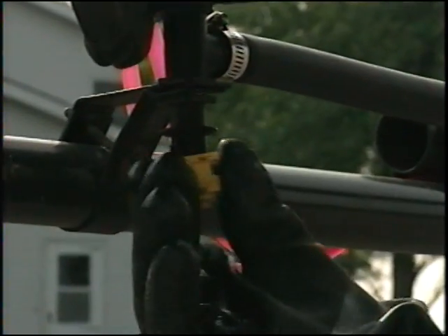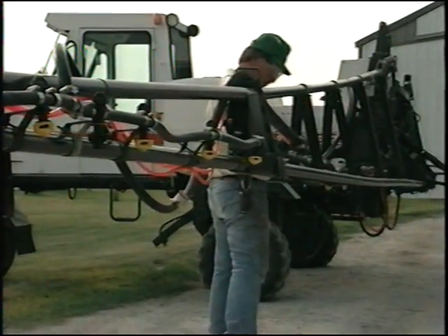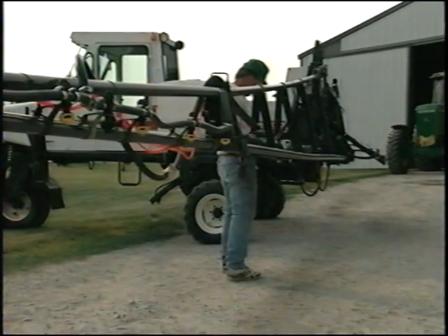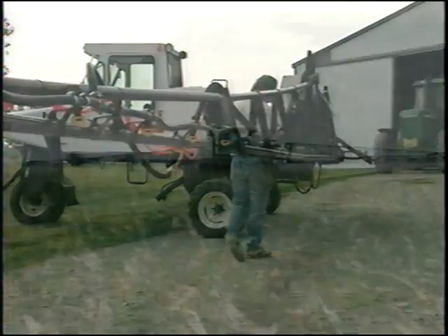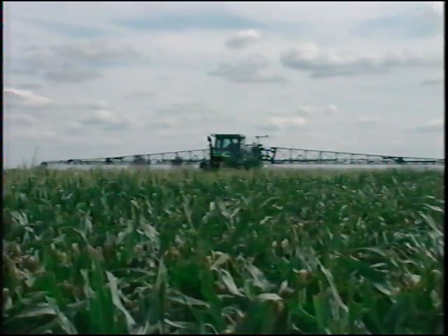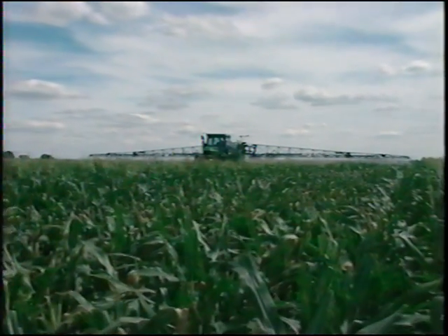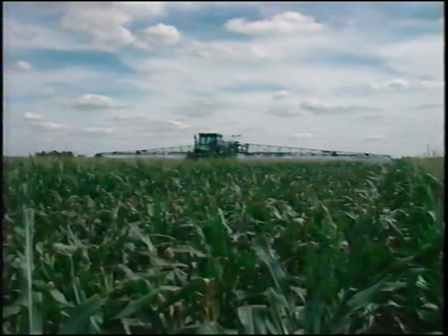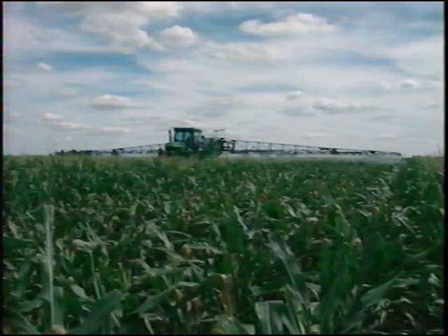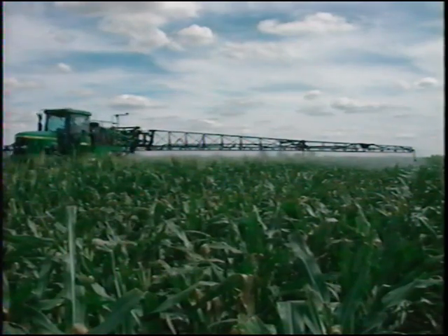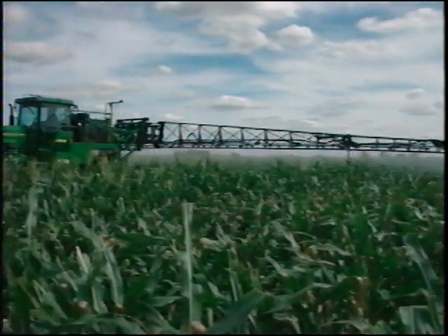And remember, using nozzles with larger orifices and lowering spray pressure, practices that automatically reduce drift, will also reduce nozzle wear and tear, further reducing drift potential. Finally, the simplest and cheapest equipment factor in drift management also may be the most important: spray boom height. The correct height for any system is determined by nozzle type, spacing, and spray pattern angle.